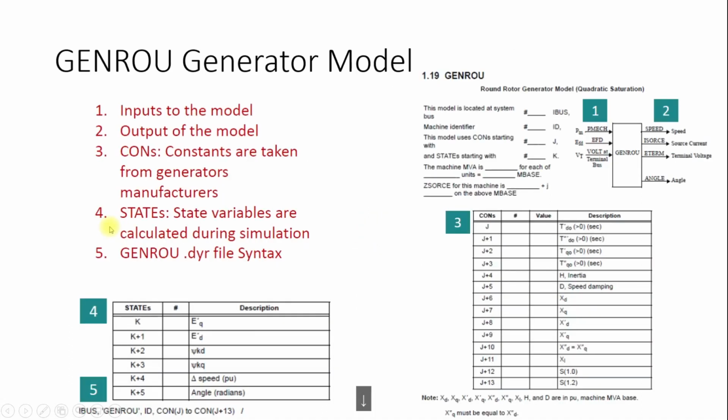Now in PSSE, how can we see this? A typical structure in PSSE is something like this. When you go to the drive where you have installed PSSE, you are going to find a folder in Program Files known as PTI. In this folder, there will be another folder known as PSSE 32 or 33 or 34 or 35, whichever version you are using.